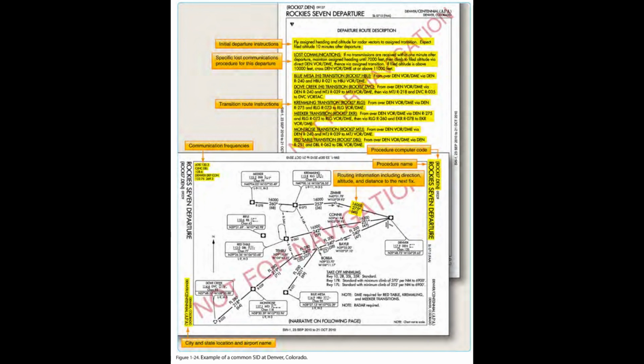Figure 1.24. A radar SID usually requires ATC to provide radar vectors from just after takeoff. ROC is based on a climb to 400 feet above the DR elevation before making the initial turn, until reaching the assigned route or a fix depicted on the SID chart. Radar SIDs do not include departure routes or transition routes because independent pilot navigation is not involved. The procedure sets forth an initial set of departure instructions that typically include an initial heading and altitude. ATC must have radar contact with the aircraft to be able to provide vectors.